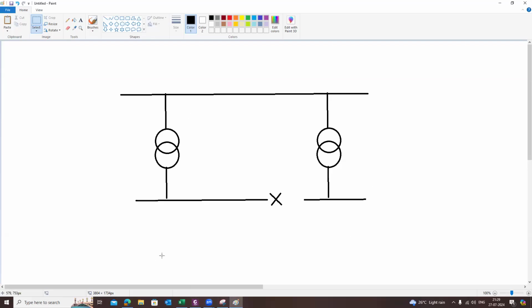So this is a very simple network. It is a 2 incomer and 1 bus coupler configuration. Normally here, let's put 1 breaker here and 1 breaker here, and these are supplying the loads. So in the normal configuration, this breaker is closed, this breaker is closed. That means the load on this bus will be fed by this transformer, whereas the load on this bus will be fed by this transformer. So individual transformers are feeding the individual buses.